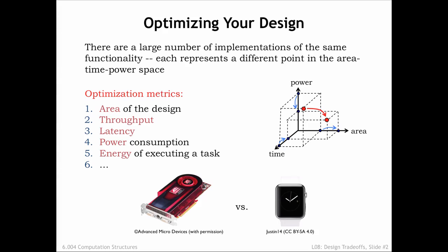The team building the watch has very different goals. Size and power consumption are critical, since it has to fit on a wrist and run all day without leaving scorch marks on the wearer's wrist. Suppose both teams are thinking about pipelining part of their logic for increased performance. Pipelining registers are an obvious additional cost. The overlapped execution and higher T-clock made possible by pipelining would increase the power consumption and the need to dissipate that power somehow. You can imagine the two teams might come to very different conclusions about the correct course of action. This chapter takes a look at some of the possible trade-offs.